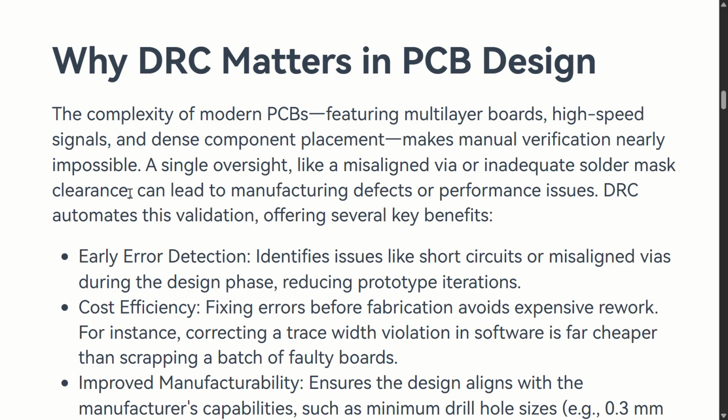So if you place two copper traces closer, even less than 0.15 mm, there is a probability of trouble during actual manufacturing, because design precision alone is not enough. Those who manufacture the PCBs have machinery and equipment, and those also have limited precision. All machines may not have high precision and accuracy; there are always some hardware limitations.